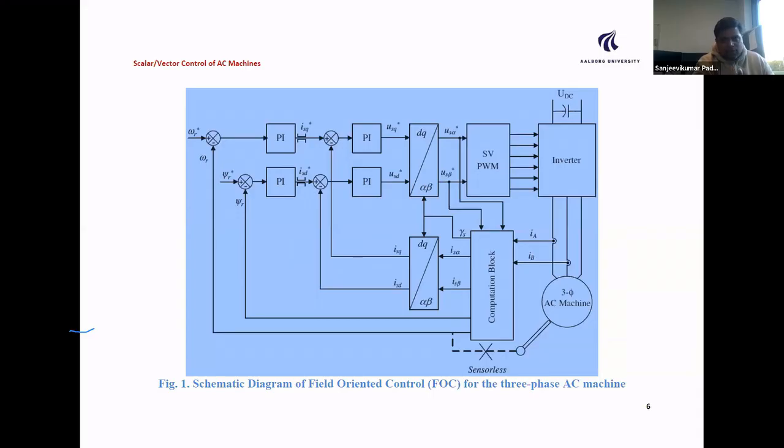It's nothing but tan inverse of y by x or x by y. So we have two parameters, beta and alpha. So tan inverse of y by x. So you can easily calculate what is the rotating angle of the rotor. So that angle has to be fed here because we need to rotate all these blocks to synchronize with the speed of the rotor. So this is a natural formula. There will be an angle required in these blocks.